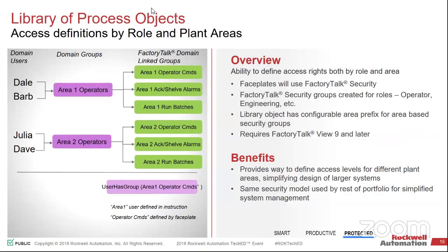Now what you can do is that same user level can be tied in through the groups. So I can now nest all of this operation, put groups around it. Keep wanting to do a pointer. There we go. So now you can go in there and tie in the security that you would normally have as part of your administrative groups, your engineering groups, and your operator groups, and pass that all the way through your HMI system.